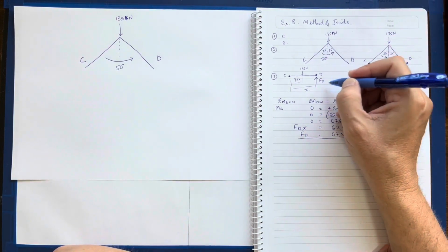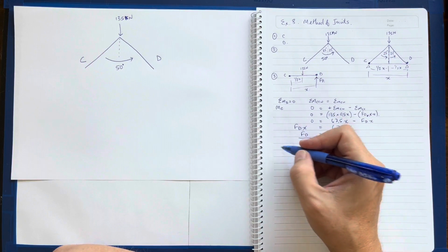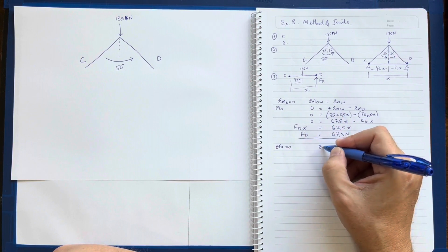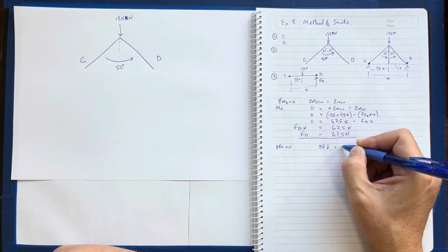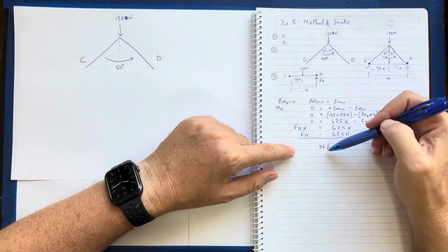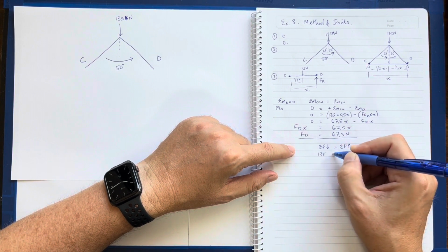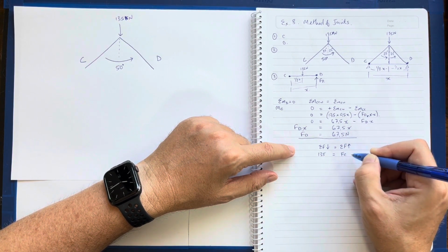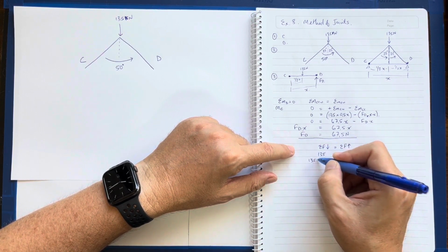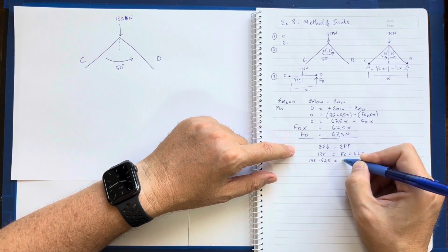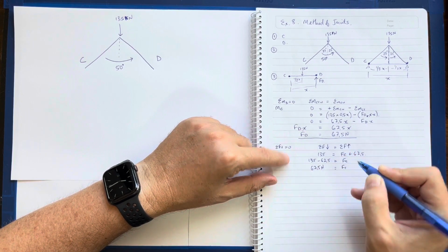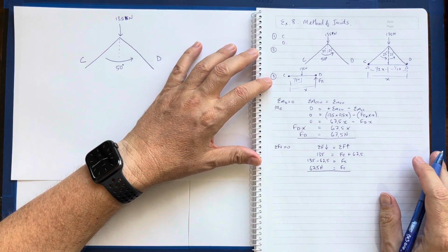To prove that I know then what the force at C would be, I do the sum of the forces vertical equals 0. Sum of the forces down equals sum of the forces up. All the force down is 135, which equals the force of C plus 67.5. That goes over to that side. 135 minus 67.5 equals force C. The force at C is 67.5 newtons upwards as well. There we go.